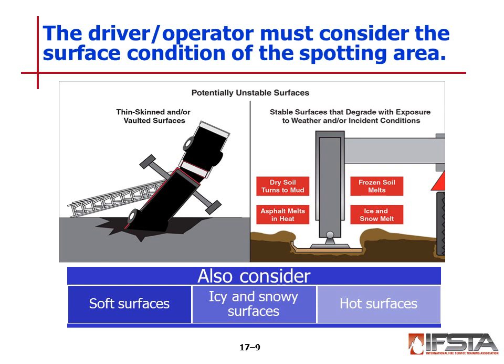Pre-incident plans should identify parking lots with potential for stabilization problems. The driver operator must be aware of areas that may contain surfaces that cover underground vaults. Vault surfaces may be created by underground parking structures, utility chases, drainage culverts, basements that extend under sidewalks, and underground transportation systems. Manhole covers are good indicators of underground voids.